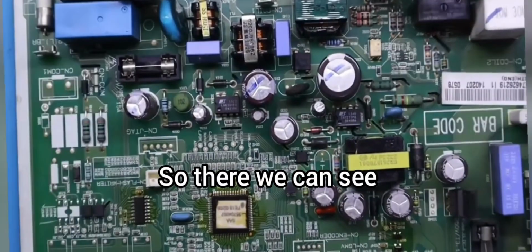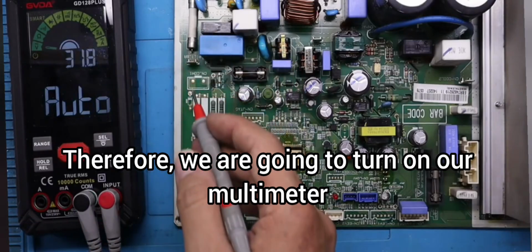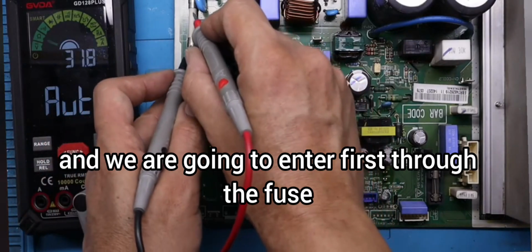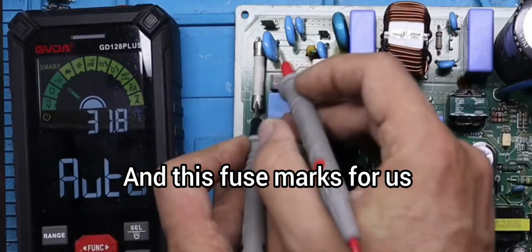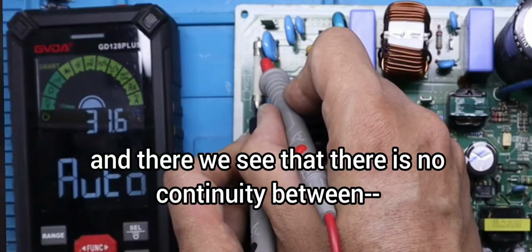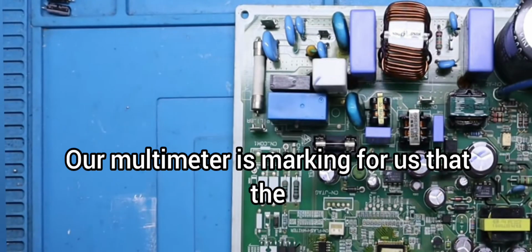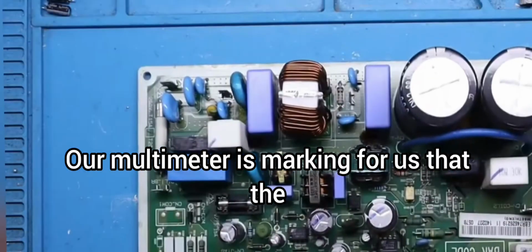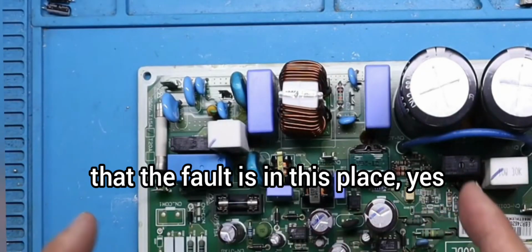Yes, so there we can see that there is a large spark mark. Therefore, we are going to turn on our multimeter. And we are going to enter first through the fuse to see what the fuse says. And this fuse marks for us that it is dead. It has to have continuity. And there we see that there is no continuity in the fuse. Our multimeter is marking for us that the fuse has blown. So what we see is that the fault is in this place.